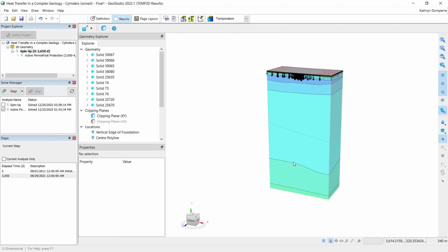You will notice that the nonlinear temperature contour in the center of the domain is reflective of the sloping contact surface between the ice-rich silt and the underlying materials. Thus, the geology at our project site had a larger than anticipated influence on temperatures below the ground surface, and indicated 3D heat transfer was present even without the presence of the building.